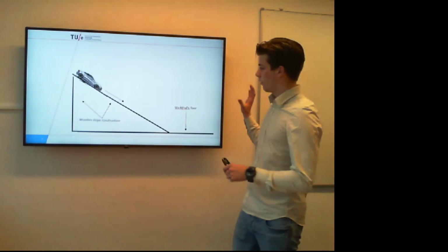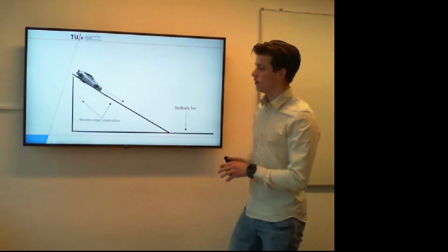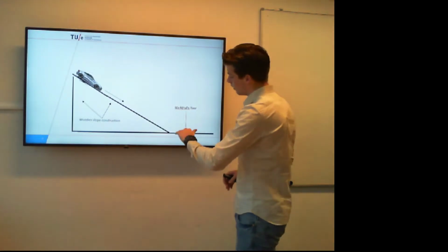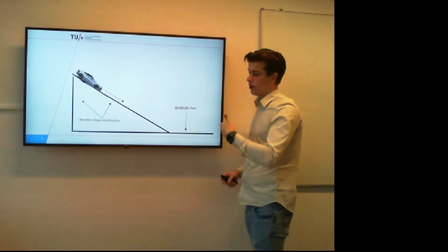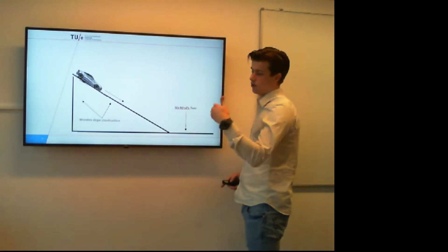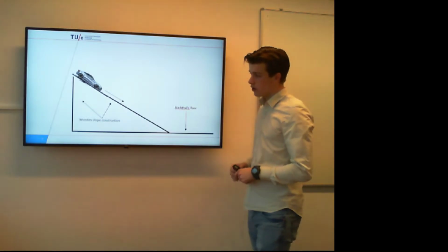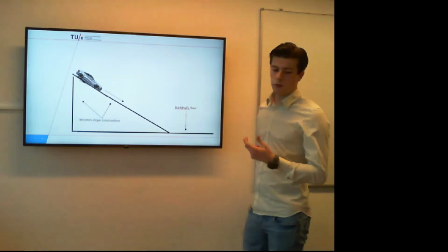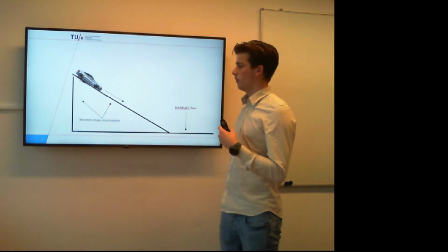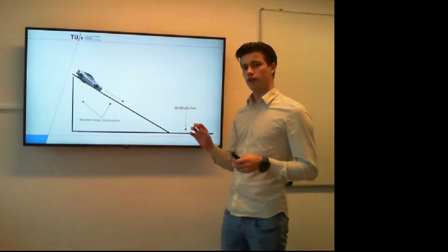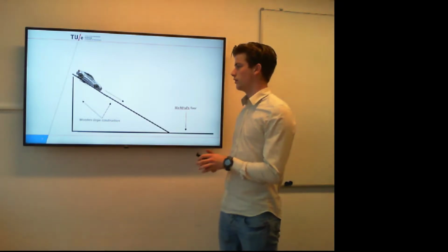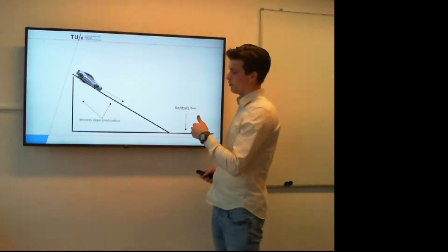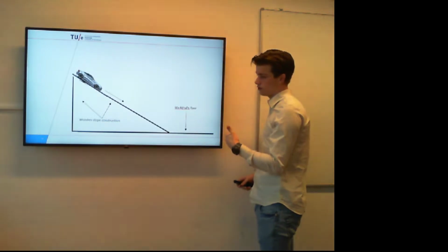This will be the test construction. There will be a slope that will create an initial velocity, and then there will be the floor on which the car will be coasted down. From the top of the hill to the far end, the speed will be logged, and with the time differences and the velocity at certain time instances, the acceleration can be calculated, or actually the deceleration on a flat surface.